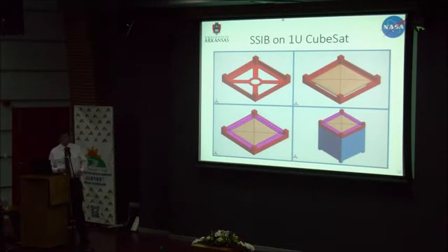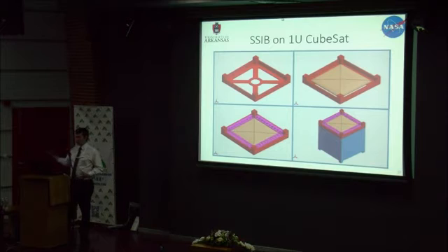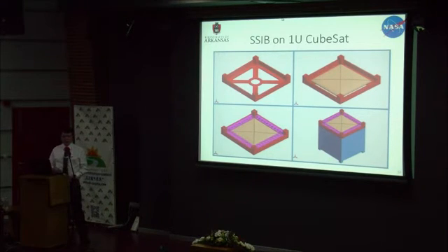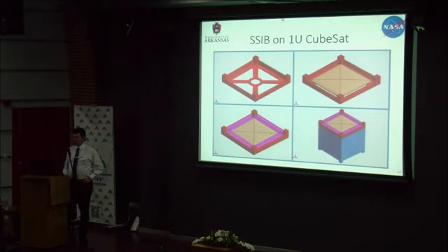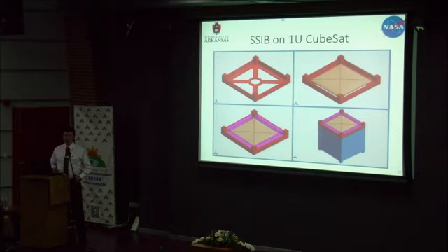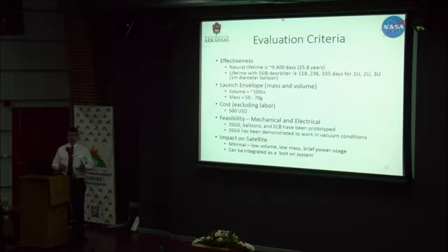So that's one of the things we'll be testing this coming summer, is how big we need to size these clips so it stays in on launch, but is also able to come out on deployment. We have a test campaign planned with NASA Ames Research Center. We're going to do TVAC, we're going to vibe test, simulate launch loads, and we're going to deploy in vacuum conditions. So I wanted to address your evaluation criteria real quick.